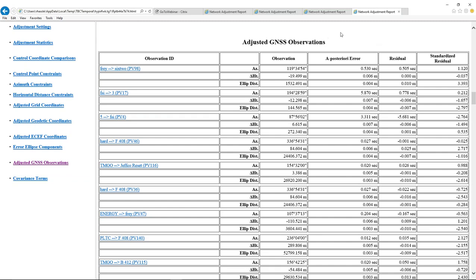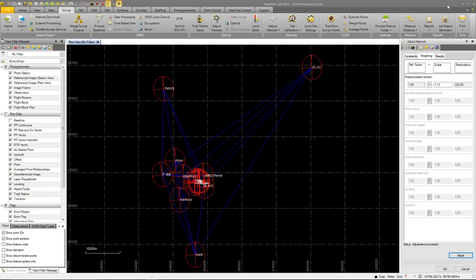All right, at this point, I'm done my minimally constrained adjustment. I feel confident that my network fits together well enough and I can continue on. That means that I will no longer change the weighting for any of my error estimates. I'm assuming they're done properly now, and the next step is for me to go to the constrained adjustment and start to fix my values.